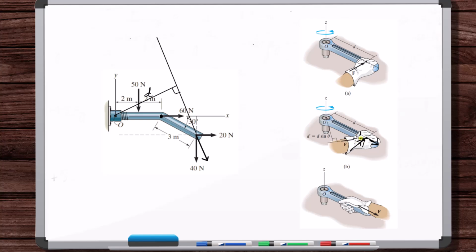It's saying F sine theta. It's getting the component and leaving that original distance the same. In other words, for this scenario, if we did R cross F here, what it's doing in the background is taking the magnitude of F and finding that sine of theta, finding the moment arm, right? The theta is somewhere in this triangle, and you're getting this component with the sine of theta, the D, or it's breaking the force down into the corresponding components that way.